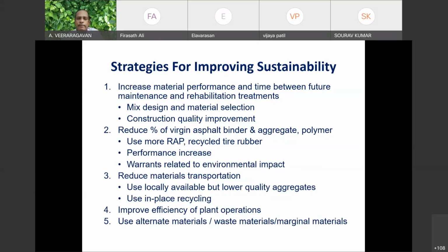I take the locally available soil. I test the soil and its properties. When you test the soil, what is the property that you test? You do a wet sieve analysis. Never ever do a dry sieve analysis for a soil. Always do only wet sieve analysis. Look at the fines passing through 75 micron, number 200 sieve. That is a culprit in most of the cases.